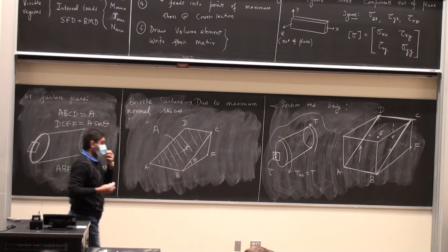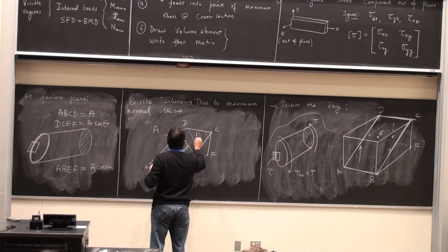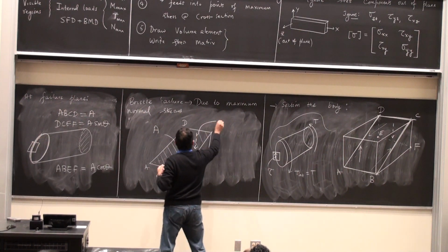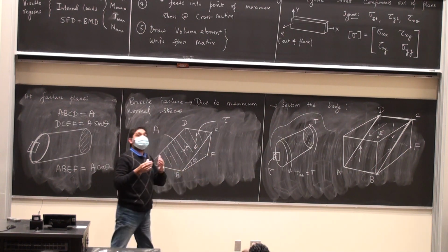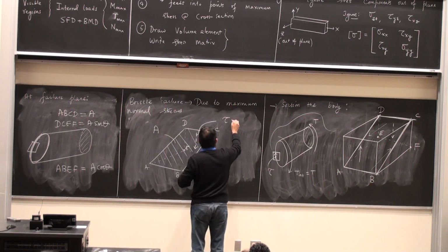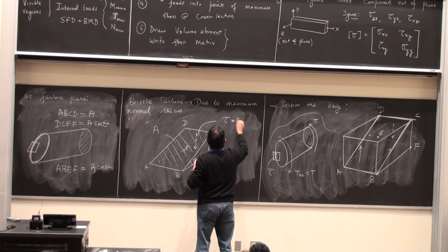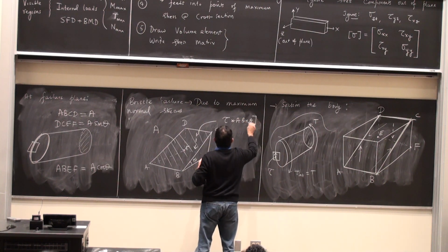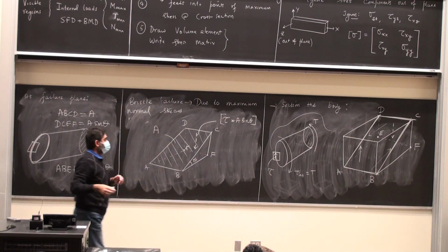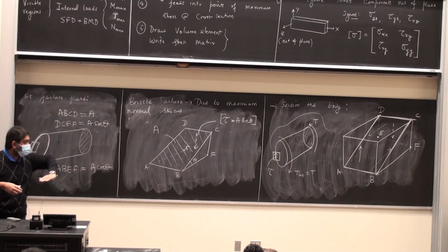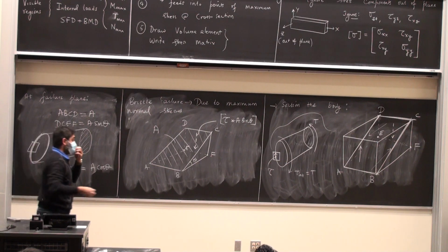You agree with me, right? So there is a shear stress here, tau. I'm multiplying it by the area, it becomes a shear force. So this is going to be A times sine theta, and then there is also a shear stress at the bottom on the face ABEF. That becomes a force if I multiply it by A cosine theta.